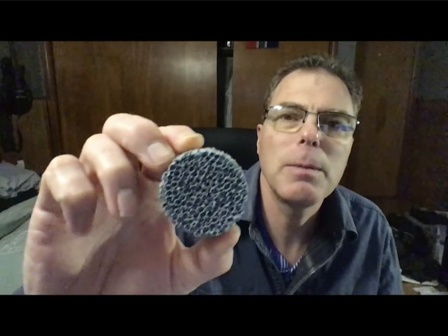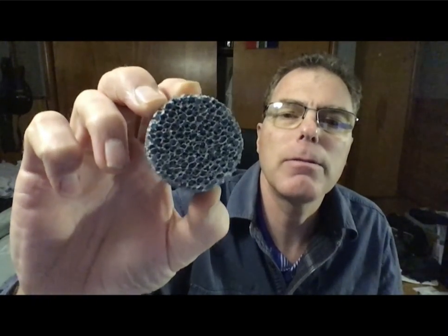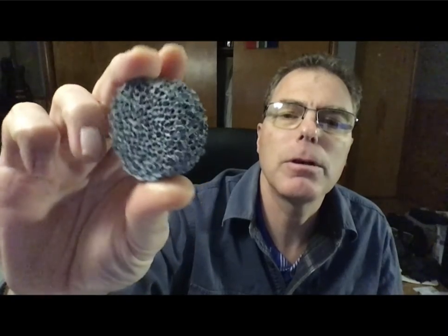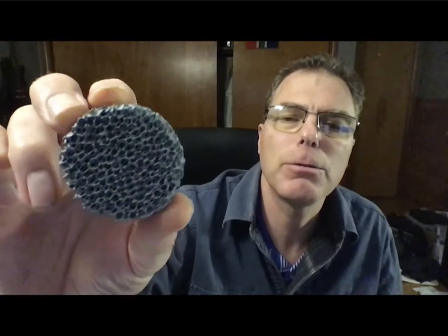Here's one here. And so it's a ceramic foam. And when the metal flows through it, little particles of oxides and stuff get filtered out. And so they can make big sheets of this stuff. So you can have it on one side of the furnace and have the metal kind of flow through it to get to the other side of the furnace. Or you could run it through this launder where there's little filters in it or something like that. So you could filter it and degas it, and you're really going to improve the quality of the metal.